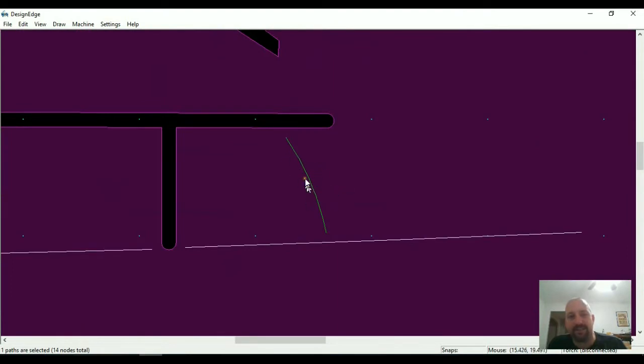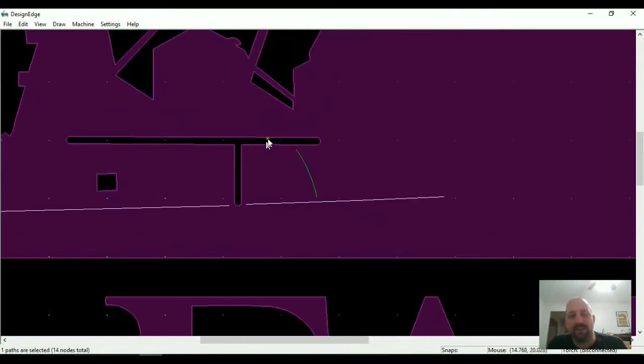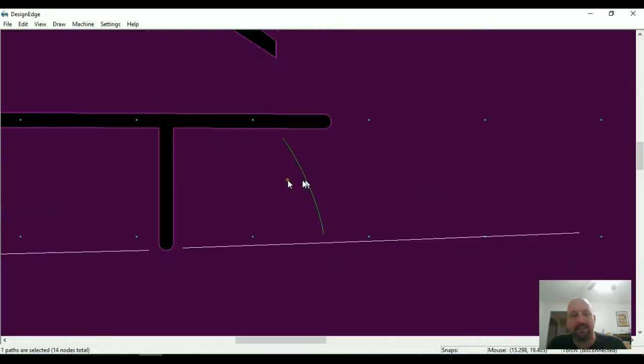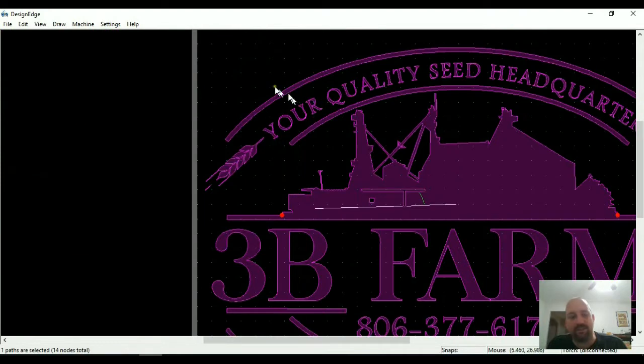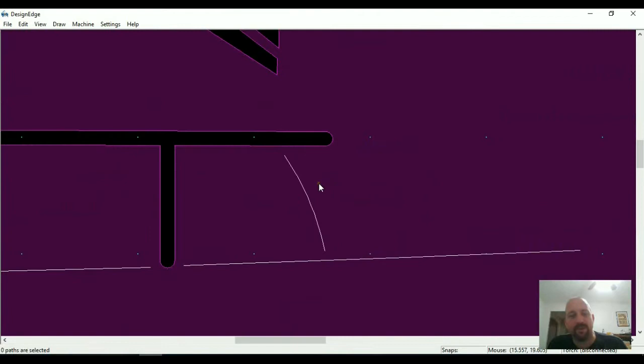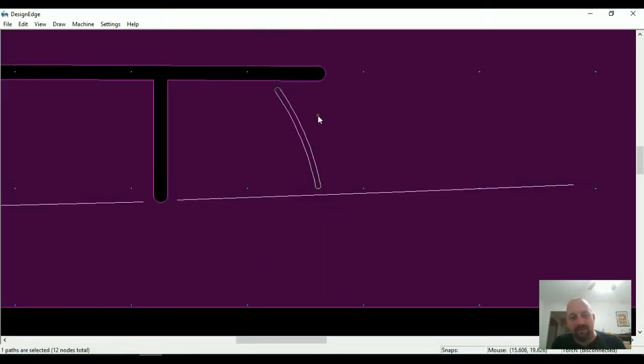For cutting it, I can leave it like that. But for looking at it, for seeing how it's going to actually cut, that won't work. So what I really need to do is make myself, I'm going to draw a circle off up here out of the way. Because what I'm going to do is Q 0.045, which is my curve. I'm going to E endpoint. Just like I did before, I'm going to C copy, C center, E end. Offset 0.045/2, hold the control the first time, let off the second, trim that out.